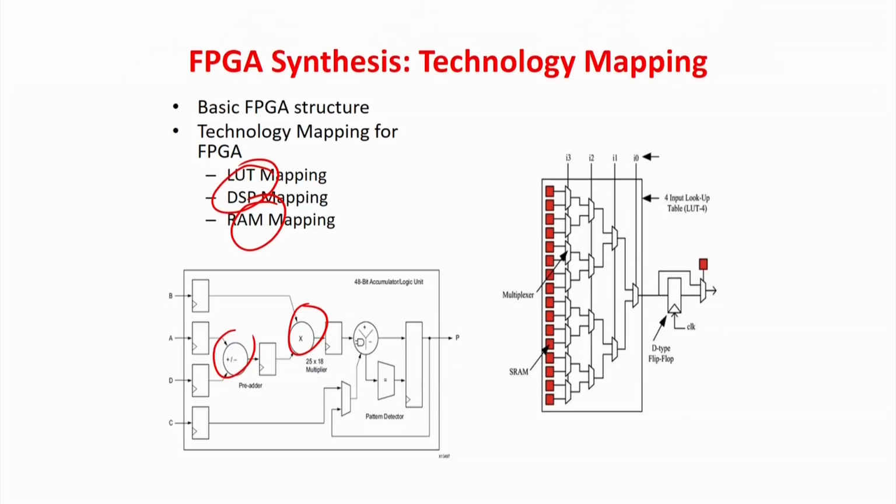So basically it is called a field programmable gate array. The same thing can be used for an adder, a multiplier. Tomorrow you can implement a processor, the day after tomorrow you can make an image processing block, because you do not require any fabrication for that. So that is now very popular, because to go to a fab and fabricate a circuit is a very expensive procedure. As very sophisticated FPGAs are available which can fit even very large circuits, a lot of market is coming into the picture.